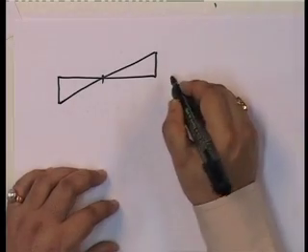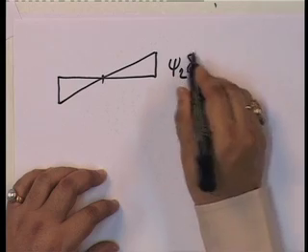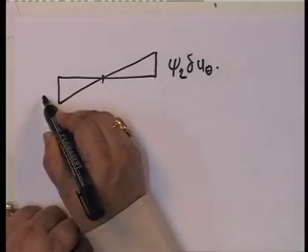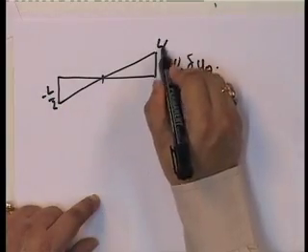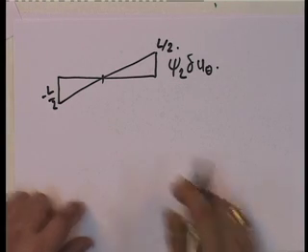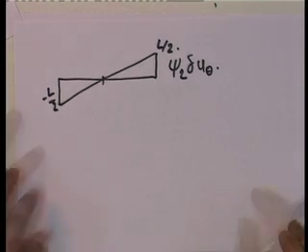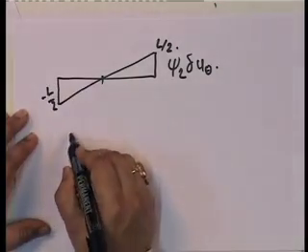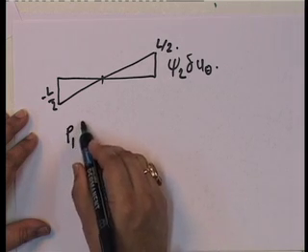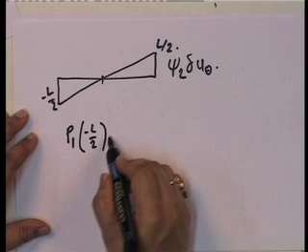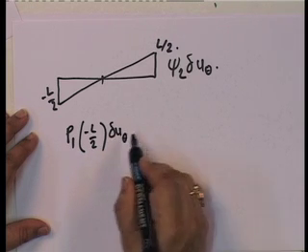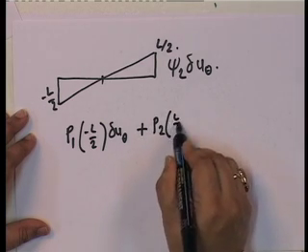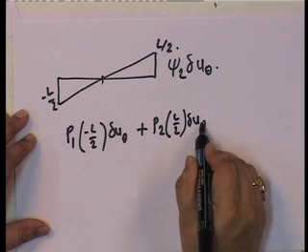So, the obvious one to do is a virtual displacement pattern which is like this, where this is minus L by 2, this is L by 2. If you give this pattern, then what does the virtual work equation look like? Let us start. The first one is that P1 here. So, P1 is being subjected to this plus P 2 into, right.